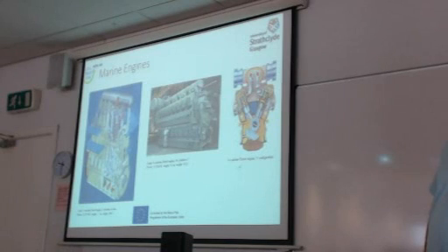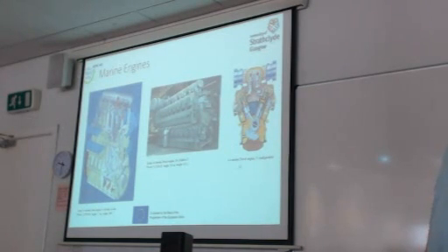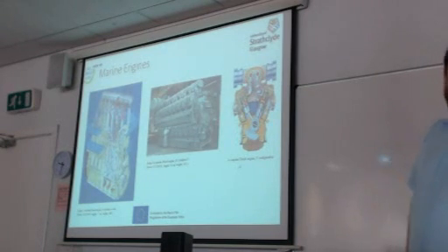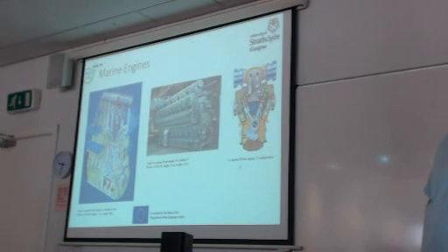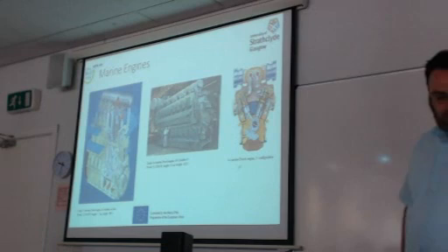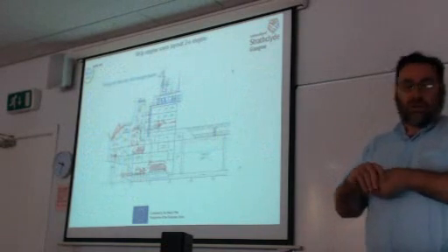So the size of these three types can be seen in this slide. Starting from the left picture with a typical large two-stroke marine diesel engine. Of course, nowadays this engine model can be used also in dual fuel mode. And then we have in the middle a medium speed four-stroke engine, and then on the right we have a four-stroke high-speed engine. Medium speed and high-speed engines are four-stroke engines, whereas the large slow-speed engines are two-stroke engines.